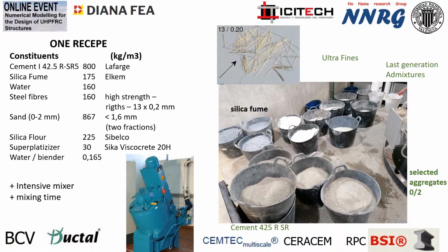That also needs a specific high energy mixer. It is not necessary to use the best mixer in the world, but you need to combine the energy of mixing with the time. If you have a lower energy mixer, you will need more time. And of course you use lots of fibers. This is one of those we use at this moment, 30 millimeters. You can go longer or shorter depending on your objectives. There are lots of commercial brands in the market, and you can select one. At the moment, we use our own recipe.